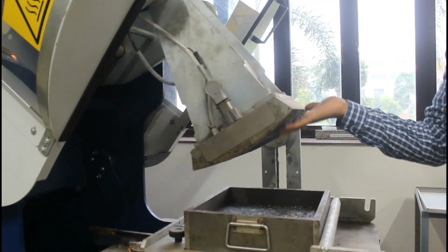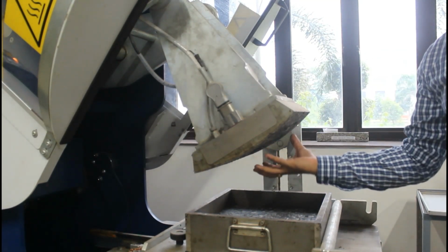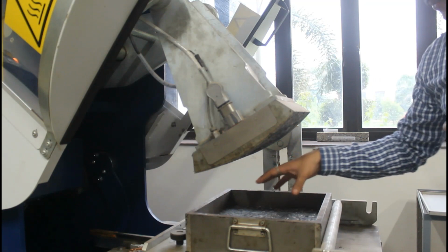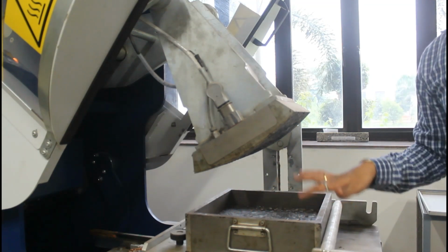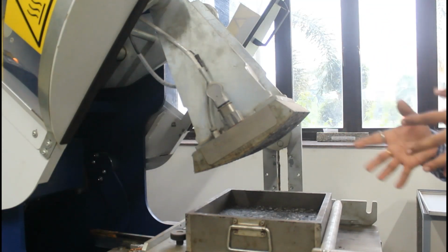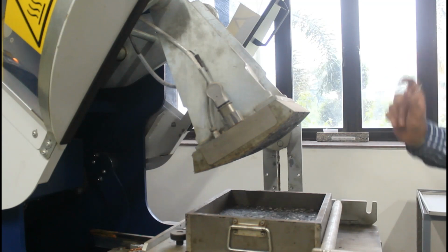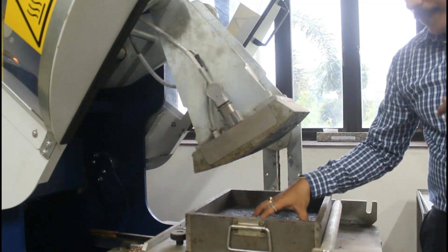Steel wheel roller, what you see in an actual roller compactor in the field. This is like a steel wheel roller, where this will compact the mix inside the slab. The compacted mix can be used in the wheel tracking device for rut testing with different air voids, different mix properties. Second and third thing, whatever prepared sample.